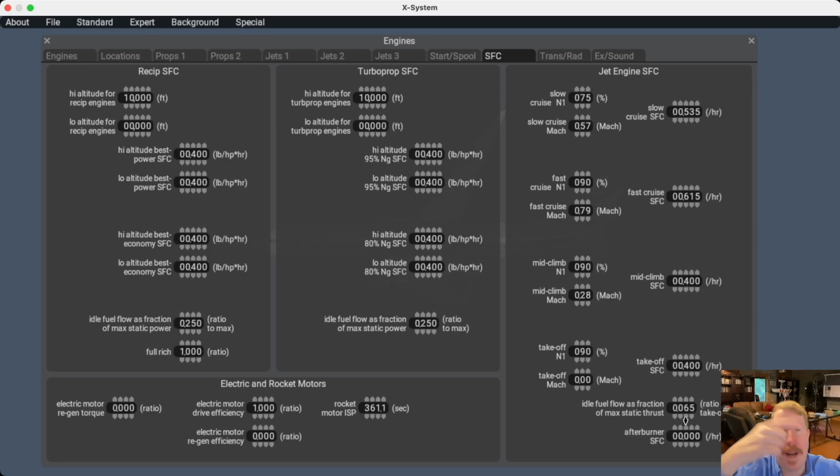There's no insulating wall of air necessary for the fan. There's no fuel associated with the fan. It's just like a propeller, basically. There's hardly any difference. And so that big fan can idle just as slow as you please. The only part they have to keep moving fast is that little turbine to keep the insulating wall of air built up, but the turbine is small. And so because of that, these big high bypass jet engines can idle at very, very low fuel flows and very, very low power outputs, which is awfully nice from an efficiency standpoint for the taxi and approach and landing phase of flight.